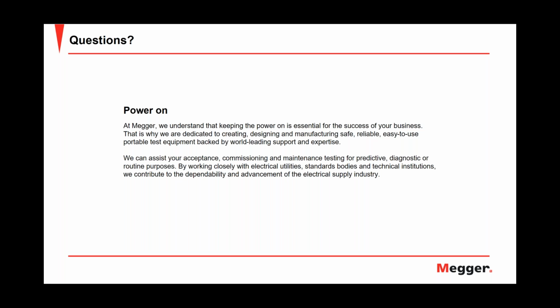So the power continues to be sourced to that area. It heats up and heats up and heats up, and it can melt the aluminum. And in copper, like I said, because copper has a much higher melting point, normally that does not happen. Unless you have a really catastrophic failure, then you might also get a melted copper conductor, but normally it doesn't happen.